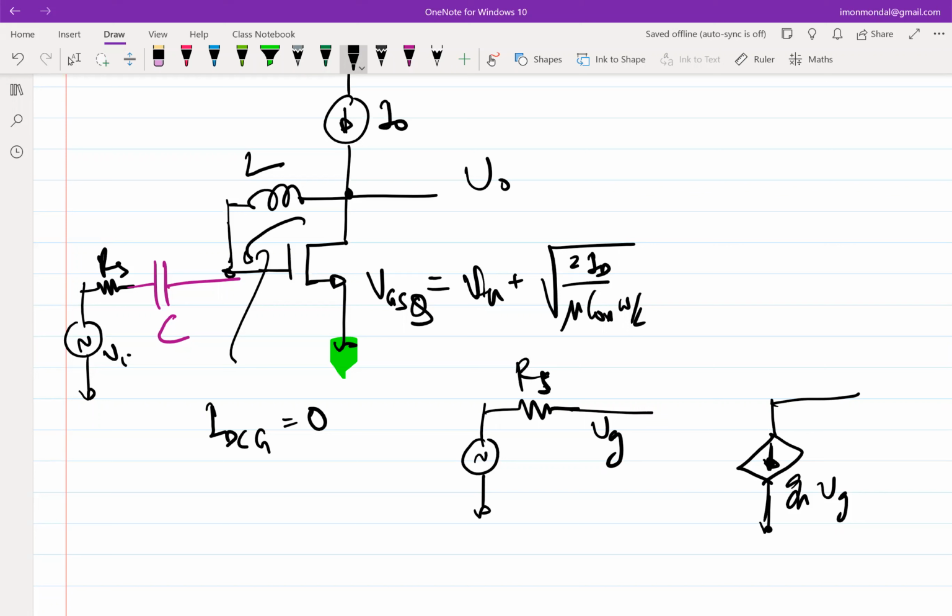But the problem is in IC, you can do it in discrete design, no problem. But the problem with IC design is that it's very difficult to make inductors on chip, unless we are operating at really high frequencies, few gigahertz or higher, right? You don't really get inductances of appreciable values, because the impedance of an inductance is omega times L. At low omega, naturally the impedance is lower.